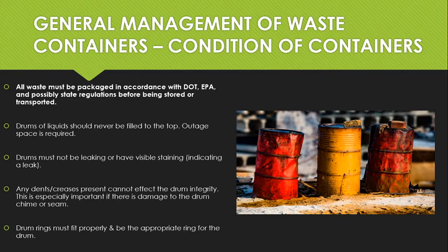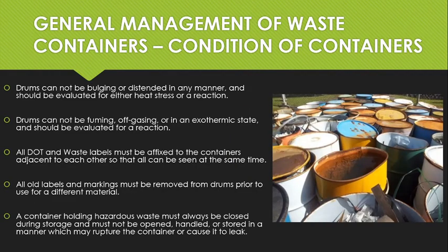And the disposal facility at the end is not going to take it like that. They are going to overpack it, and then charge us more than we would have if we did it ourselves. So just pay attention. If it looks nasty, then overpack it. Just more examples, if there's any fuming, off-gassing. One big thing is that if there's any old labels or markings on there, whether it's an old product label or an old waste label, make sure those are removed, or just put a piece of duct tape over it or something to indicate that label is no longer applicable.